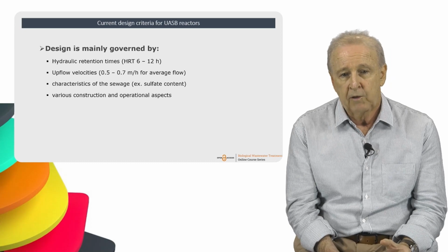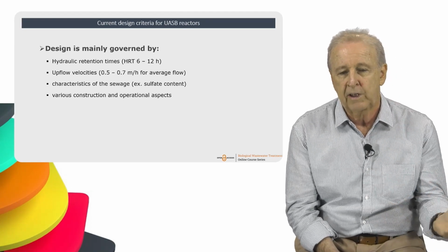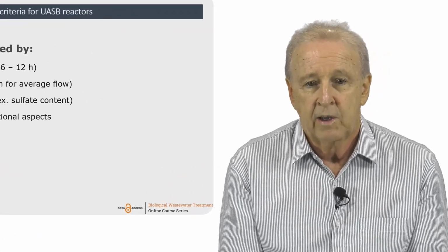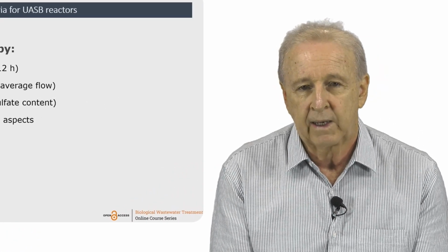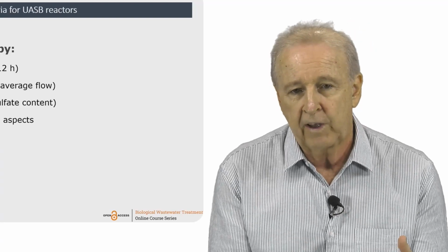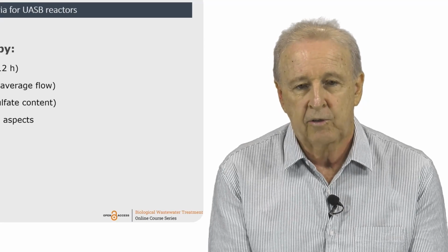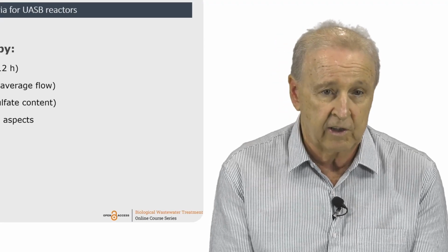And also, if you produce H2S in the effluent, because the sulfate will be reduced to H2S, if we have one aerobic post-treatment unit, this sulfide concentration will demand oxygen for its oxidation.